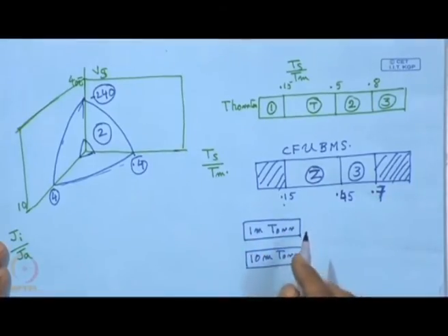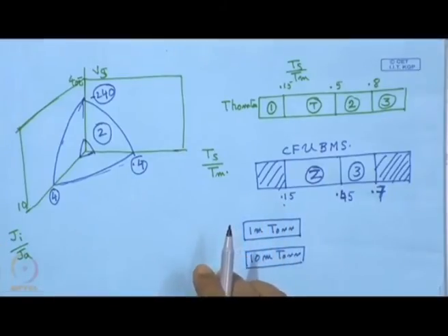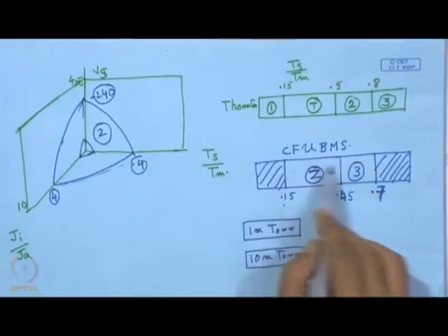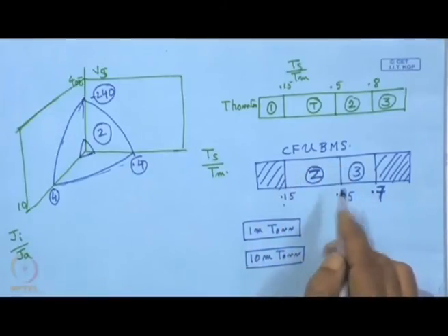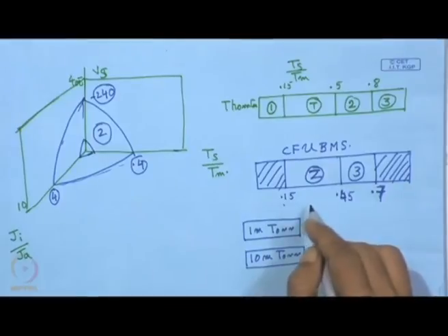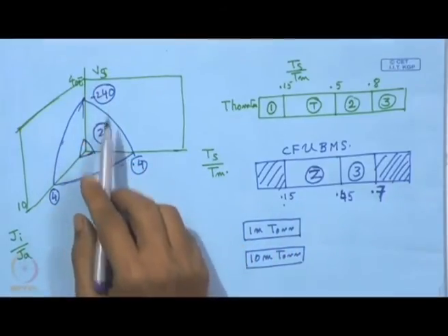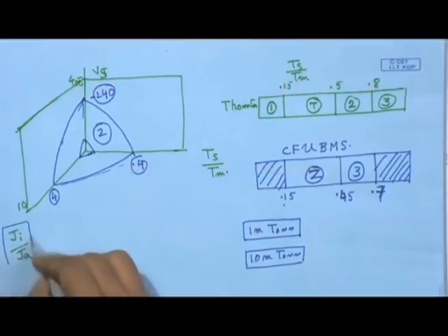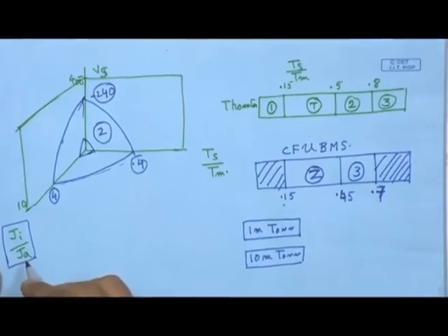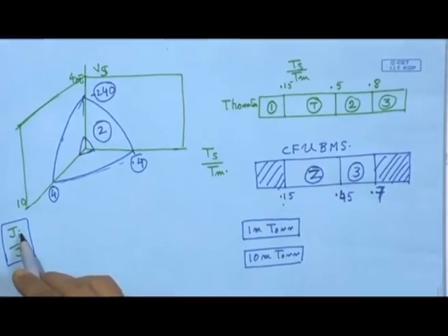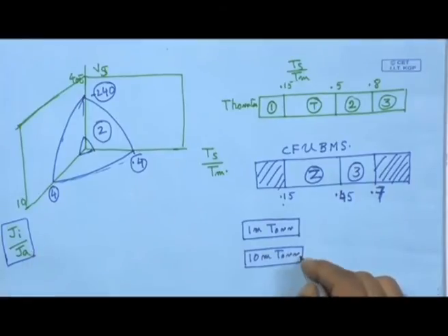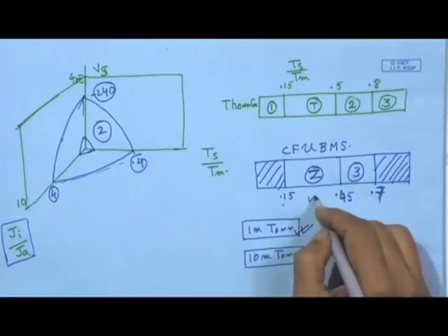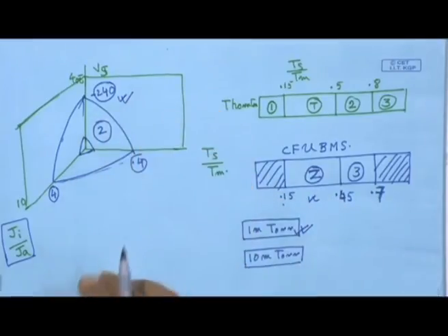So, with this unbalance, one can find the advantage in this zone structure, which we can achieve at a low sputtering temperature and low pressure. What is important is that this Ji by Ja, the influx of ions by the influx of atoms, has to be increased, and that is responsible for lowering the requirement of pressure, temperature, and substrate bias.